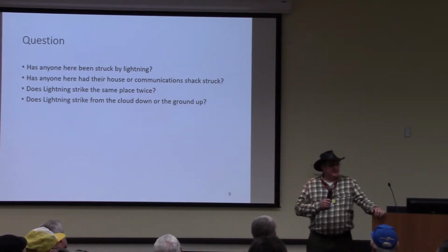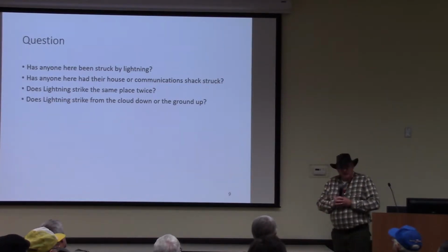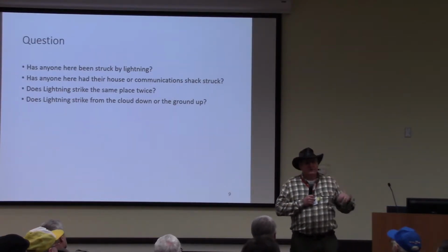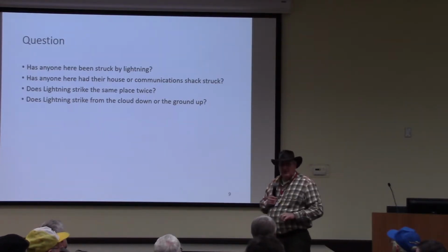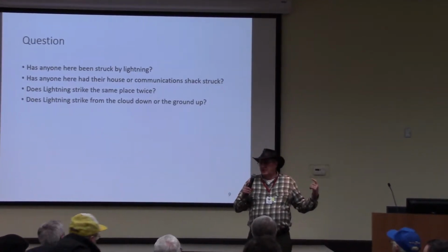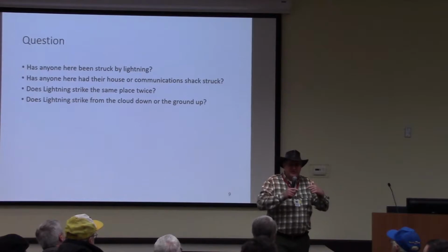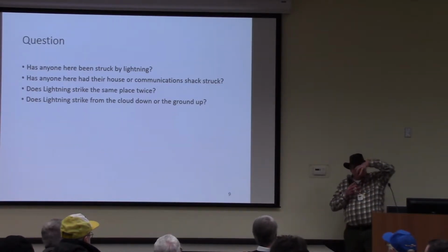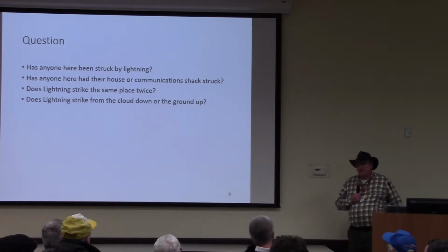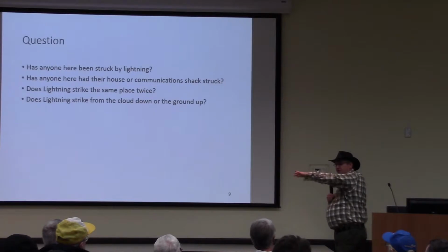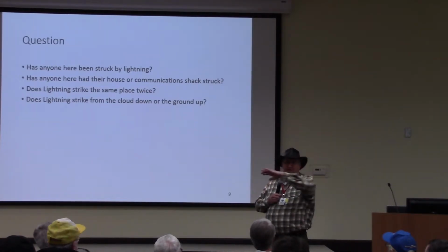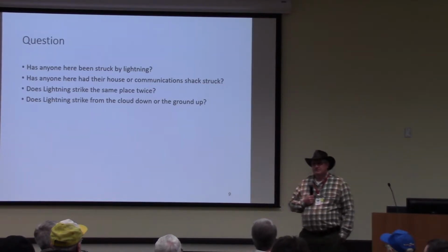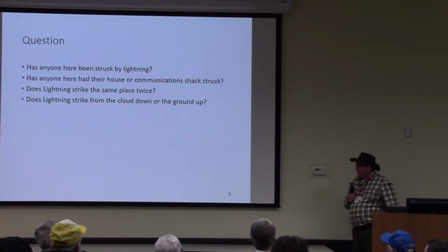And as it's dumping into the channel, the channel expands, gets hotter, wider, and more current flows through it. That's where you get your waveform. So when you see the picture where you get the flash and you see all the leaders, what you're seeing is the electrons flowing from the leaders into the main channel. And the main channel is neutralizing the potential between the two points at either end. So it's a race. That's why it's not always predictable exactly where it will attach. Given that all your heads are at roughly the same height, if the leader formation came down, you'd be drawing leaders off of every one of them. Some of you would draw more than others, depending on how conductive your skin is, because of the moisture content, ions, and things like that.